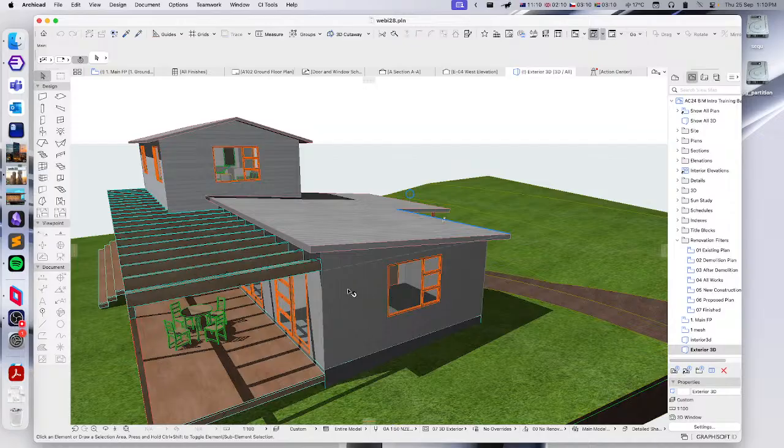So it will do all of the things that you will expect. It will be a separate element sitting alongside the wall. It doesn't become part of the wall, but it will essentially attach itself to the wall. If we move the wall, the covering will move. If we move the window in the wall, the hole that's in the covering will move with that, and that sort of thing. So what we're going to do is select our walls.